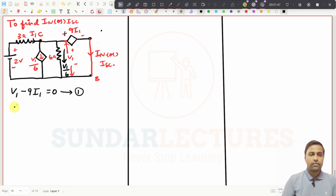And now for the second instance, I am going to write the KVL expression for this whole loop. Why am I doing that? Since I will get I1 here. It is very simple, right? So you try to understand. Start from this point, go here, come in this way, and then complete the KVL expression for the outer loop.